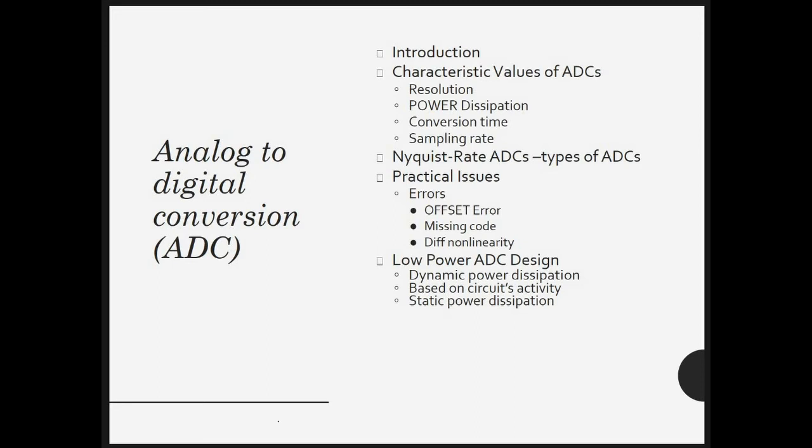An ADC is defined by its bandwidth and its signal to noise ratio. The actual bandwidth of an ADC is characterized primarily by its sampling rate and, to a lesser extent, by how it handles errors such as aliasing. The dynamic range of an ADC is influenced by many factors, including the resolution, linearity and accuracy, and jitter. The dynamic range of an ADC is measured by its effective number of bits, the number of bits of each measure it returns that are on average not noise. An ideal ADC has an ENOB, that is effective number of bits, equal to its resolution.